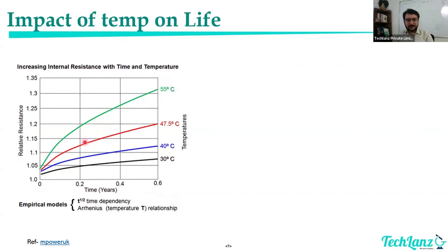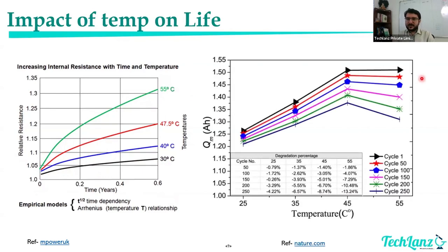But now if you see this slide, this particular thing is very evident from this graph itself. The capacity degradation at 25 degrees centigrade between the first cycle and the 2250th cycle is very less. But if you see the higher temperature, the capacity degradation, right? Because when the cell resistance is increasing, the degradation will also be faster. So the degradation of the capacity is much higher when you keep on operating at high temperature, right? This is clear.